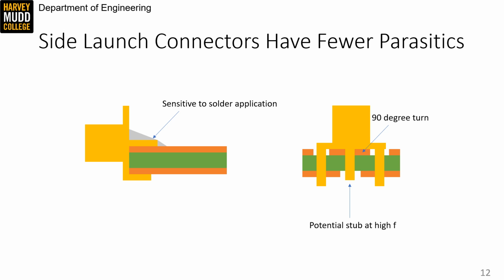Connectors also matter a great deal in the design of RF systems. They're very common failure points because they are places where a signal passes from one transmission line to another, which can cause reflections. As a result, your efforts as a designer and the quality of assembly are really crucial for connectors. I've seen lots of designs fail because of connector mistakes.